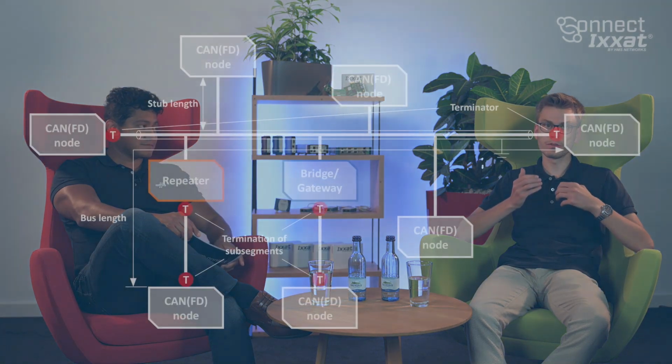One of the main reasons for them is an improper network topology. The CAN bus has to be implemented as a continuous line. Cable stubs should be avoided as much as possible, but are inevitable when nodes are connected. Up to a certain length, the signal reflections caused by cable stubs do not affect the transmission stability because they dissipate before the time of network sampling. The following formula can be used to approximately calculate the maximum stub length. It should be less than 5% of the maximum length of the bus system.